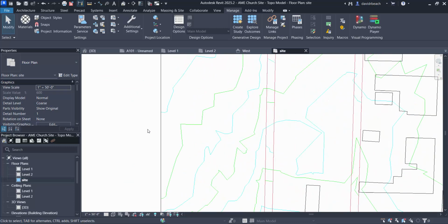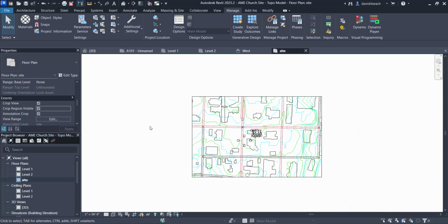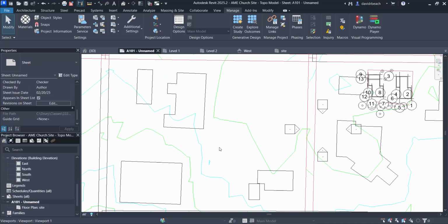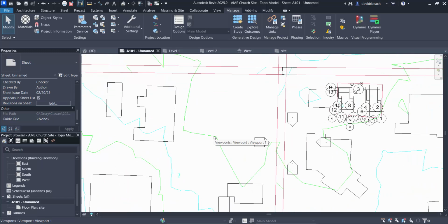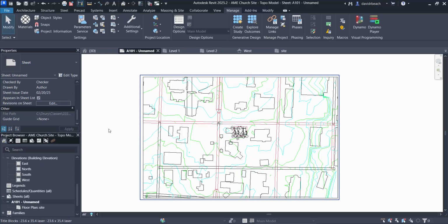Now I have something set up so that if I turn my crop back on, and I go to my laser page, you can see that I can send this now in such a way that I could say cut the greens, engrave the cyan, and then I could send a second pass that says cut the cyan, engrave the green, and that would allow me to stack those model and make a hollow topo file all the way up. And I can take that a step further as well.